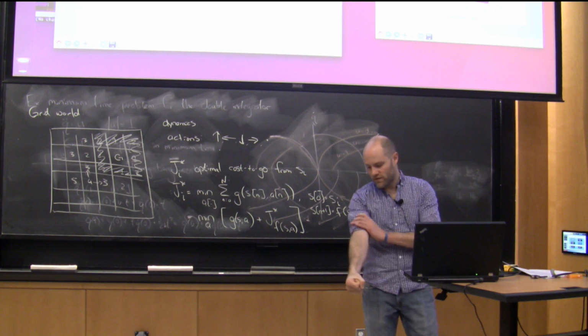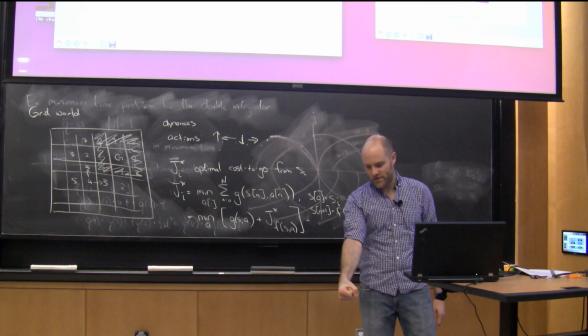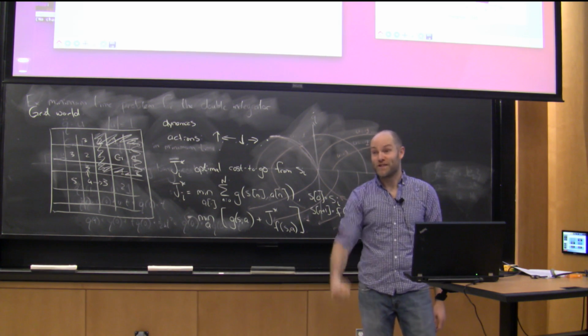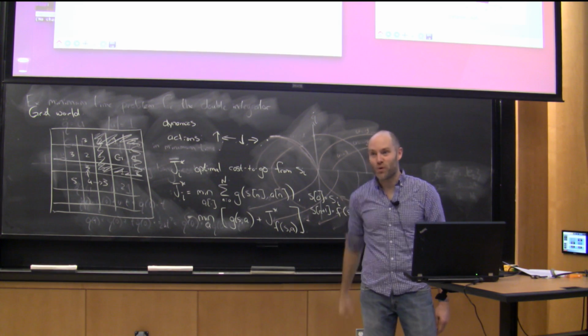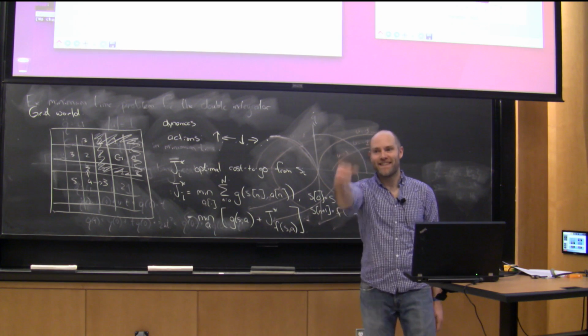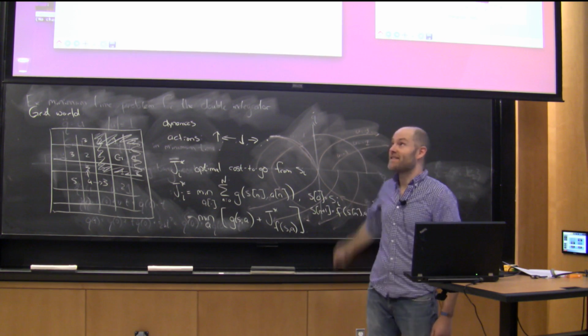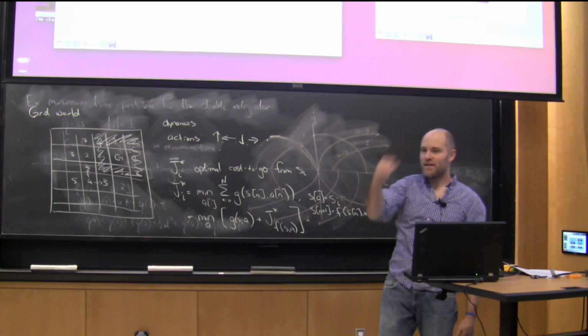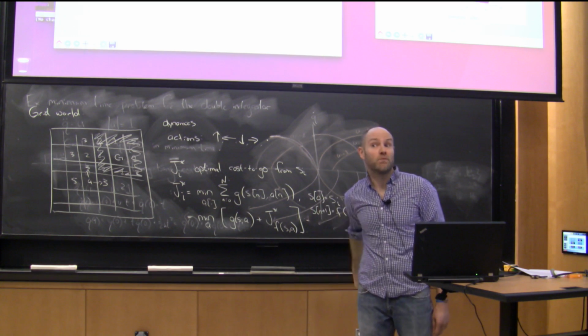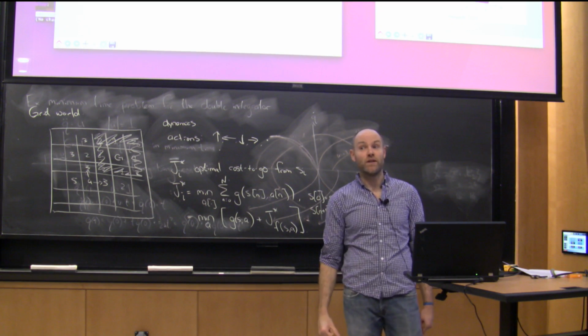A simple controller that we'll use as a baseline later is if we just look at the velocity I'm currently going and apply torque in the same direction as that velocity, then that'll always add energy. That's not so good when you get to the top. You've got to do something different. But if you just want to pump up energy, there is a simple nonlinear controller that could do it.